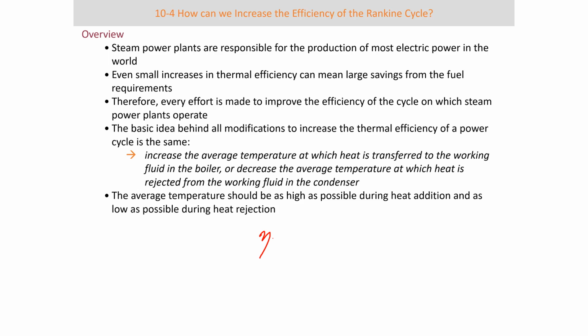Again, due to the fact that the efficiency is 1 minus Q out over Q in. So the higher the temperature that you're adding heat from, the higher the Q in. And the lower the temperature rejecting heat, the lower the Q out, and that would result in a higher efficiency.